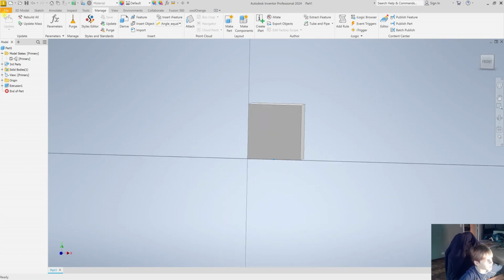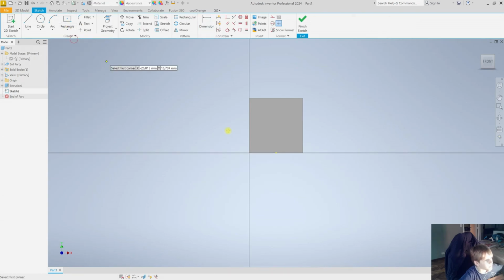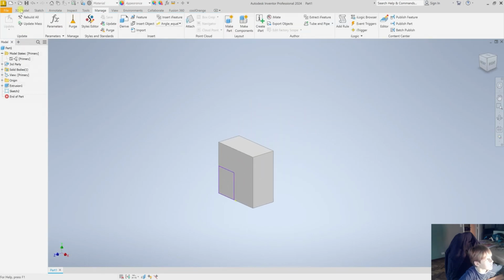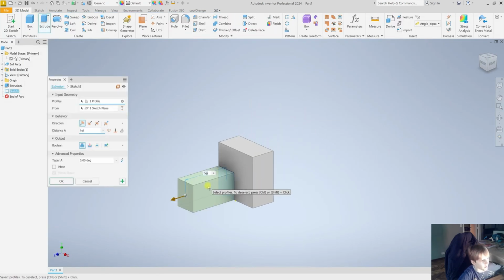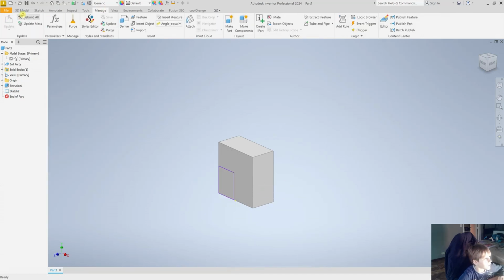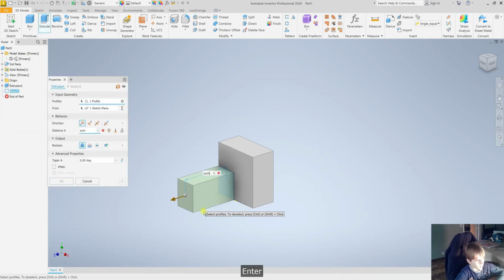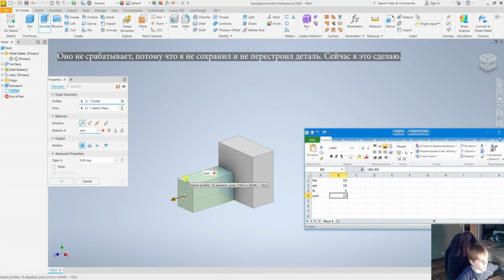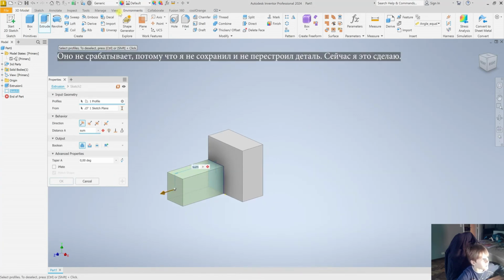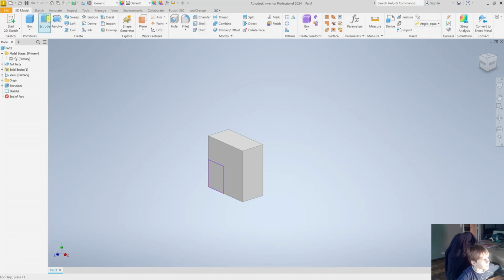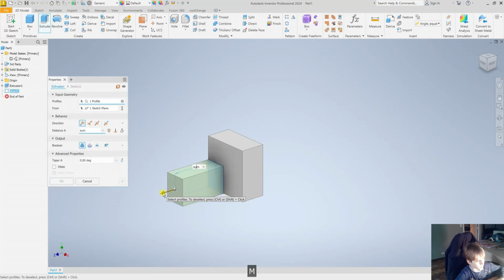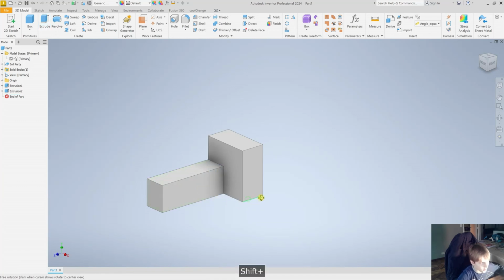For example, create another cube. First, you will need to completely finish the current sketch and then you can proceed to extrude it to the specified sum value. It needs to be rebuilt. Now the part will have a parameter, the sum. You see, we are able to extrude to the sum, and now we can effectively change this sum.